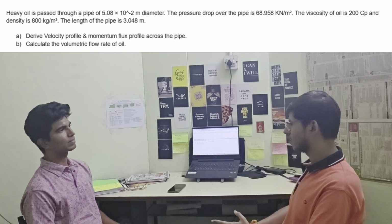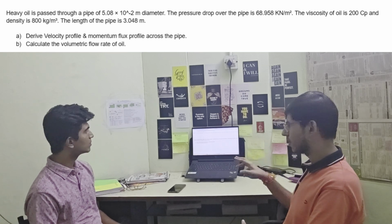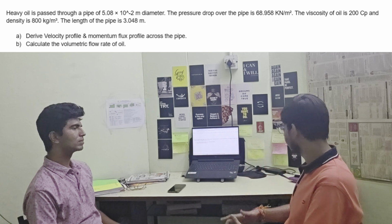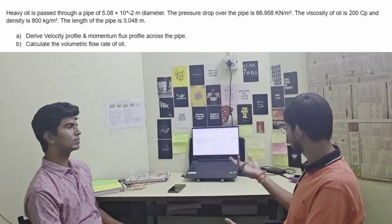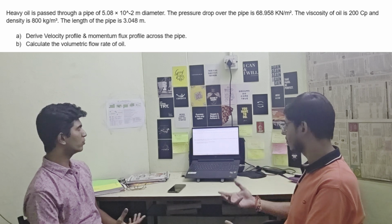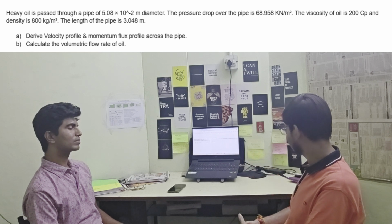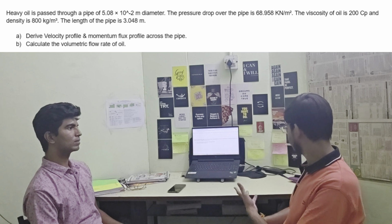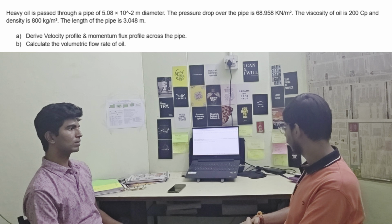So see, firstly I would like to warn you about something: the viscosity of the oil is 200 centipoise. So be careful about the units in your calculation. Don't use the 200 centipoise directly. And the question is pretty simple. You can take it to be a vertical pipe. We are assuming, take it as a vertical section, and then you can easily use the shell balance. This is a very basic case. After using the shell balance, you just need to use two boundary conditions, and after the integration you can easily get your flux profile.